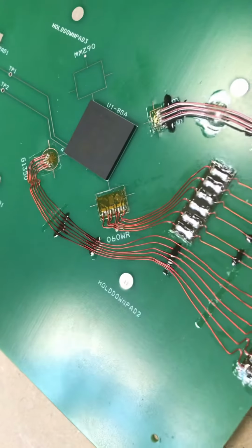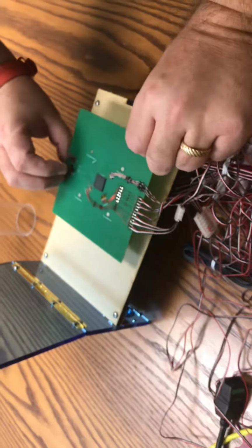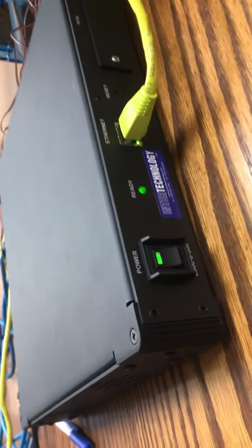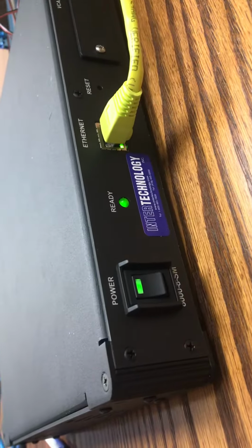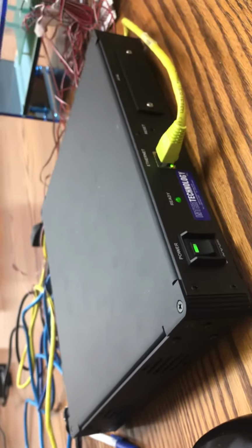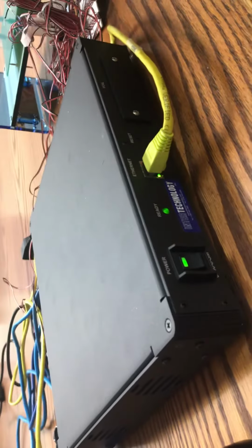I'm going to be turning that over, and we're going to be creating a dynamic strain rate test using our System 8000. Our System 8000 scans at up to 1,000 scans per channel per second, and it has an analysis tool. We use a software called StrainSmart. StrainSmart does analysis, high strain rate analysis, and it's an acquisition tool.